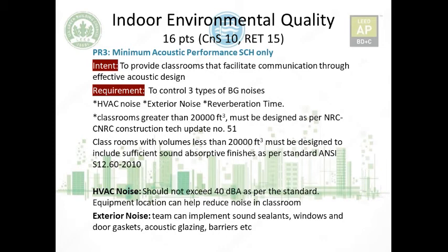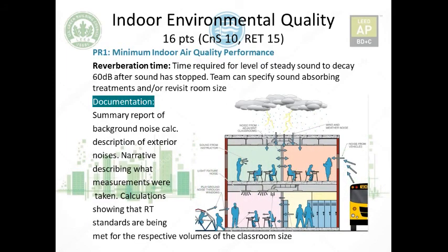Now have a look at reverberation time. Technically, it is the time required for the level of steady sound to decay 60 decibels after the sound has stopped, meaning the time it takes for the echo to go away. We saw in the requirement that for a certain volume of 20,000 cubic feet, beg your pardon, volume, the classrooms have to follow certain standards for absorptive finish. So this is how you can deal with the reverberation time.